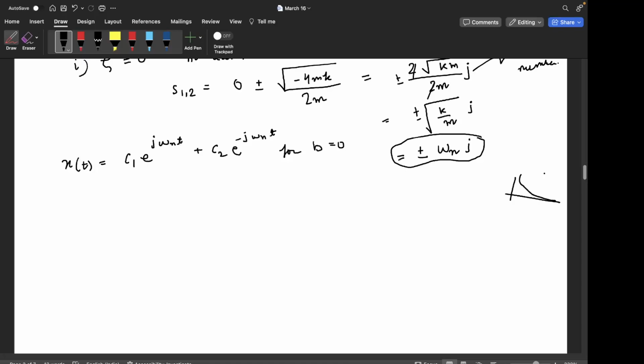Okay, sir. Sir, so here when we take xi is equal to 0, it means the spring example which we have taken here. If the xi is 0, the spring normally behaves the way it just behaves normally. Yeah, xi 0 means that there is no damper. It's just a spring, and we are considering an ideal situation, I mean that there are no other forces like drag, friction, and all to kill the oscillations. So in that scenario, if there is no damper and there is only a spring, then there will be oscillations, and the oscillations will continue